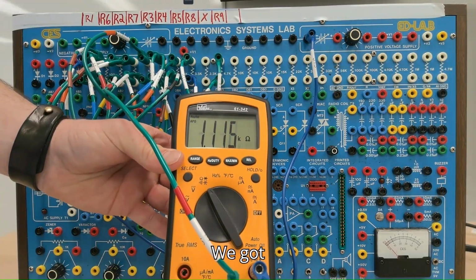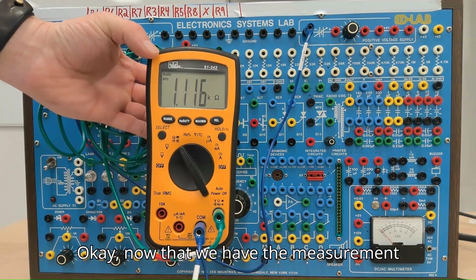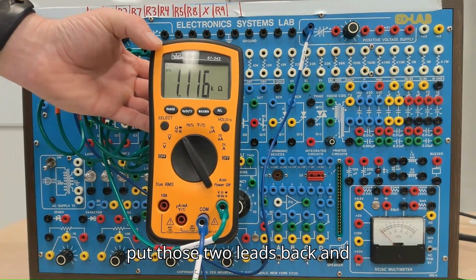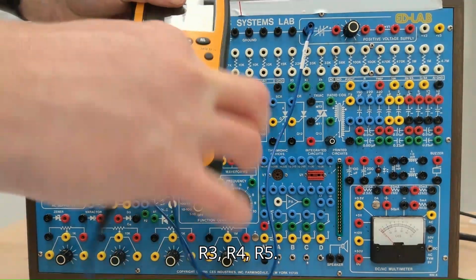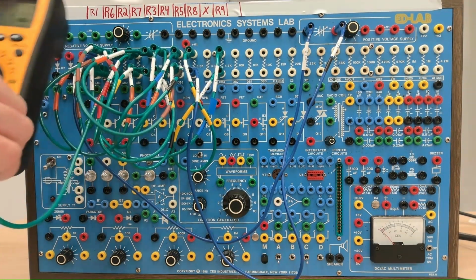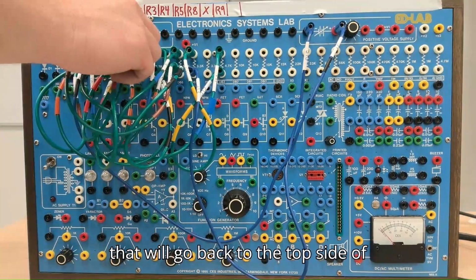We got 1.116 kiloohms. Okay, now that we have the measurement for R1, R2, we're going to put those two leads back and remove the leads needed to measure R3, R4, R5. So J1, jumper 1 back to voltage source. J3, that'll go back to the top side of R3.